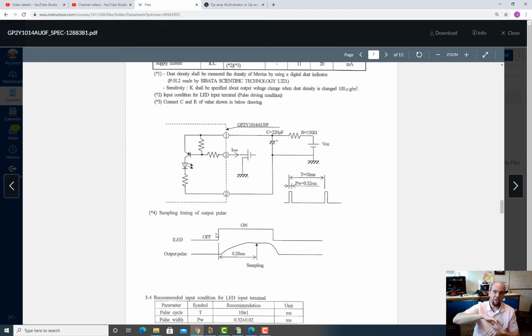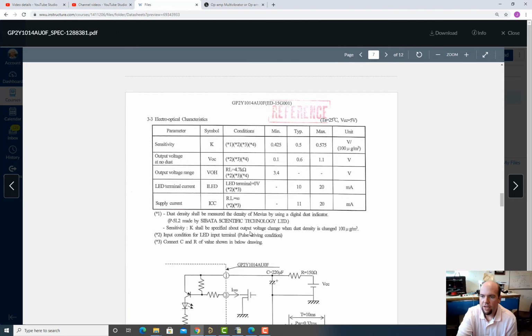So it takes this peak that comes out and does peak detection on it, and then it smooths out those peaks, low-pass filters the peaks, and then isolates that signal through a gain of 1 gain stage. So, all right, so there's your lab.